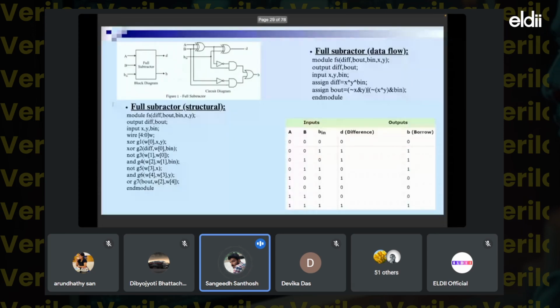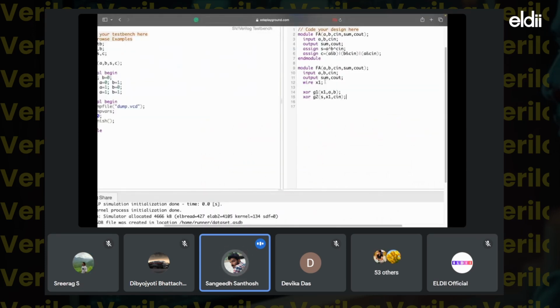So this is the full adder circuit. So we need to XOR our inputs A, B, and C in. Okay, then tell me how many wires we are going to require for carry in full adder using gate level modeling. Question is how many wires we require to create carry. Why you have said 4? Sir, 3 for the AND and 1 for the OR of the total.